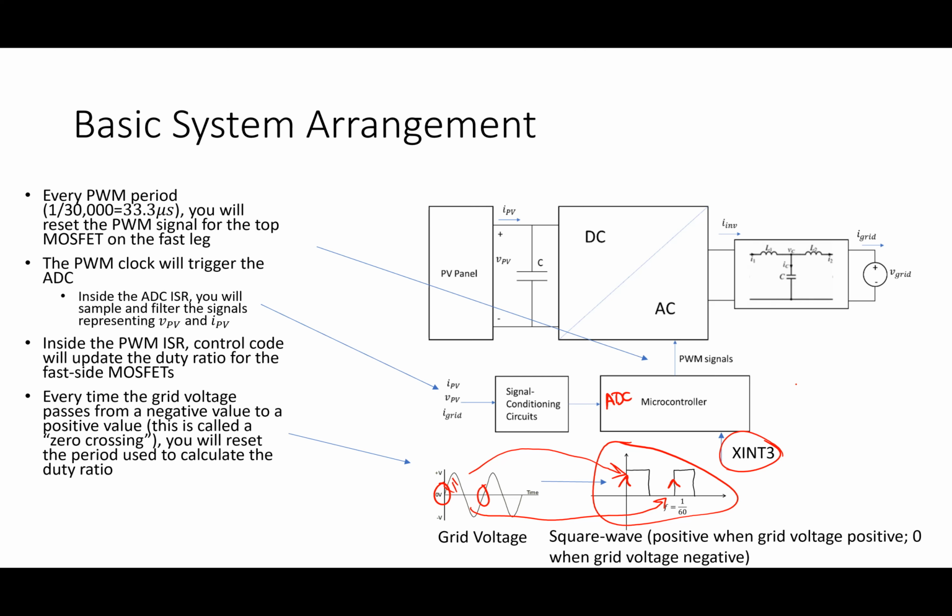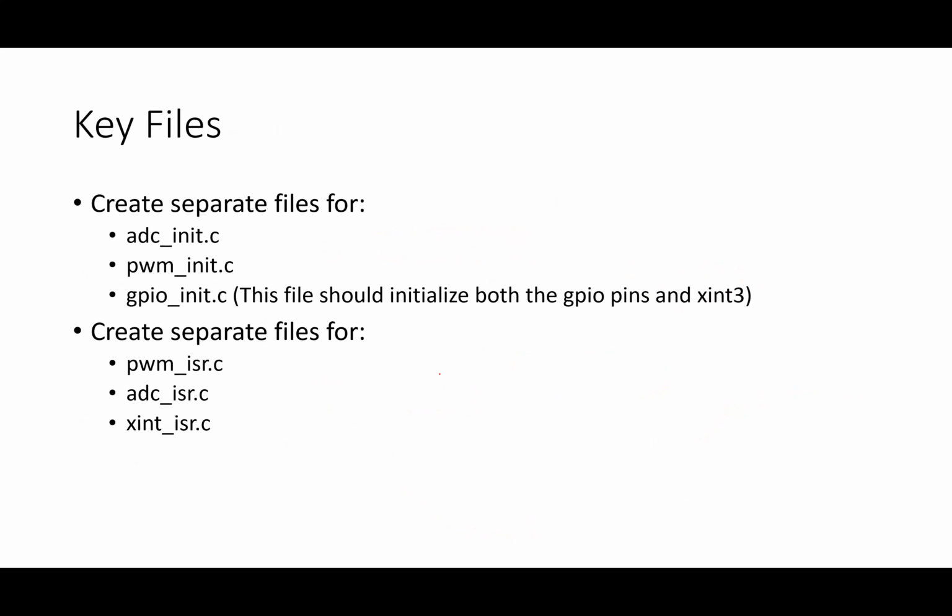Remember, I've got a 12-bit ADC, so that means I'm going to get a value out of my ADC that's an integer between 0 and 4095, and I have to figure out how that ADC integer goes back to an actual analog signal that I measured in the real world, okay? That calibration step is important. I talked about that in class. I'll do a separate video on that, okay?